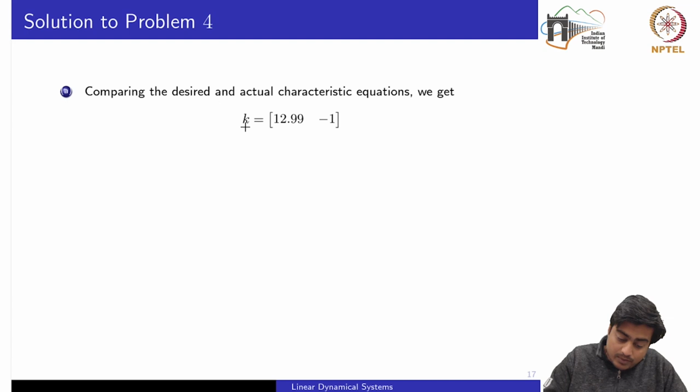So once we put this k into the closed loop, stability has been ensured, but it is not yet guaranteed whether the output is going to track the reference signal. For this, if you recall the lecture slides, we need to investigate the transfer function or the DC value of the feedback system.